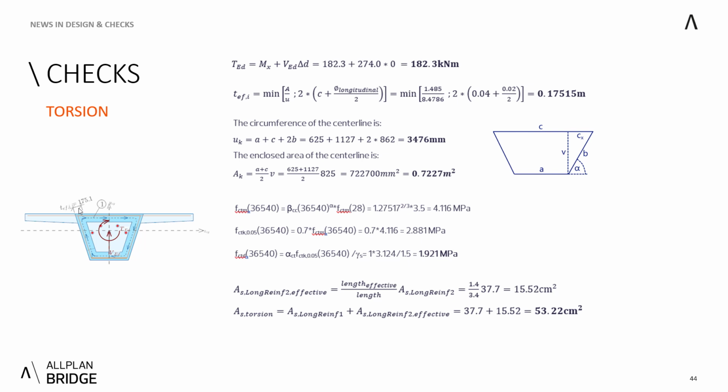One more thing that I need to explain at first is that the TEd is not just the torsional moment mx coming as a result of internal forces, but we also consider, in case of a little bit different sections, there is a difference also in this case between the center of gravity and the center of the shear.